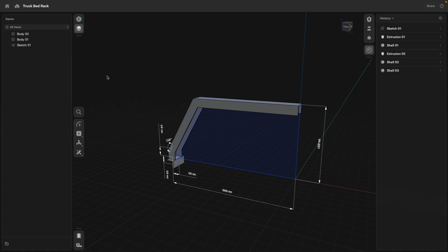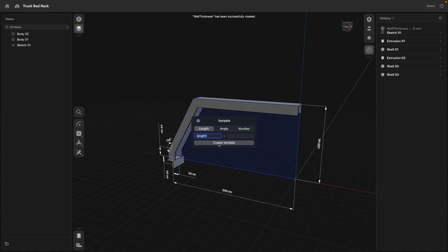This is actually now the perfect moment to show you how we can create expressions and variables and how they function. One way to add a variable is to go to add a variable. I will call this one wall thickness and specify that with 5 millimeters. When we create names, use something that's very easy to understand, also for somebody else who might have to work with your file. Very good. There we are. I create this,